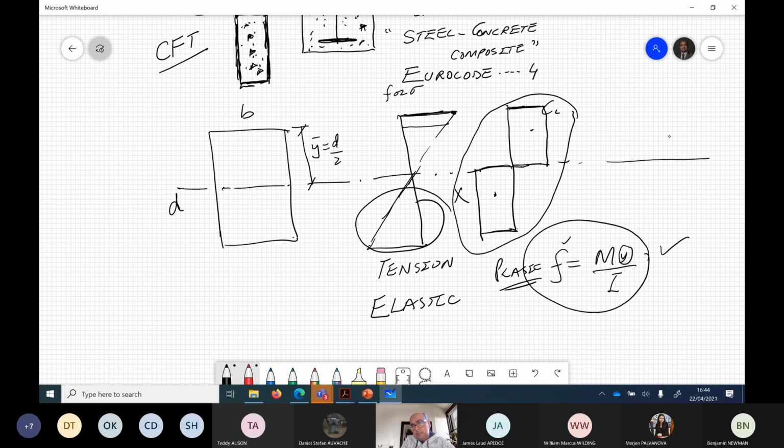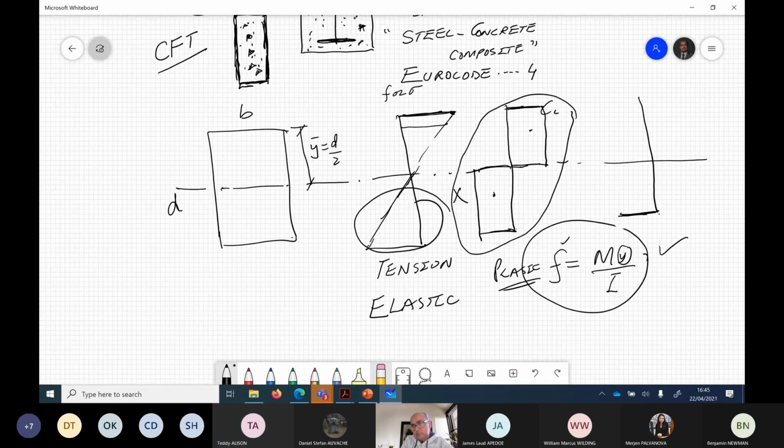So for concrete, if I'm talking about plasticity, certainly I can say that for tension, I just have steel reinforcement. So I will just have one force in the bar. Except this bit, I have nothing. There's no stress. Other portion of the beam is not taking any stress. Only steel is taking tension stress. I will just have this line which reinforcement will take care of.